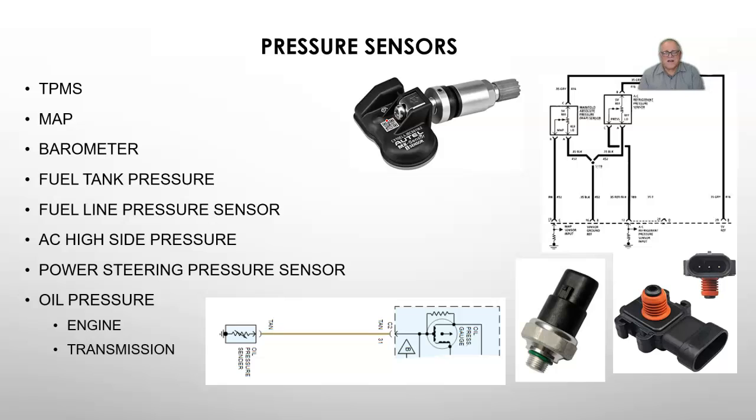It's inside the tire. If you want to communicate with it, you can do some communication from the car, looking at the dash or with the scan tool. The best way to do the diagnosing is get a TPMS tool that you can hold up to the tire and you can communicate with it. You can get its identification code, you can get the temperature inside there, you can get the pressure inside there, and it'll give you an idea of battery life, good or bad.